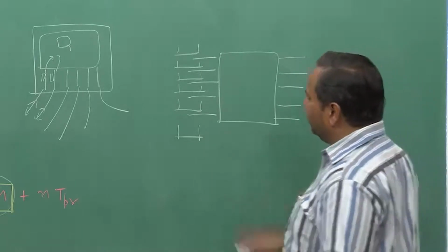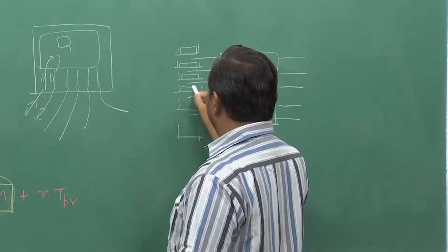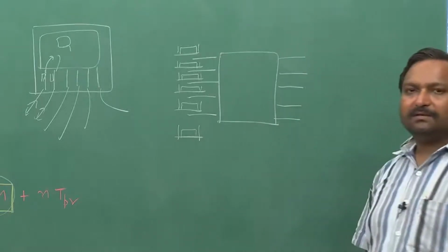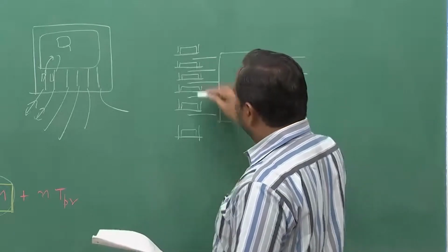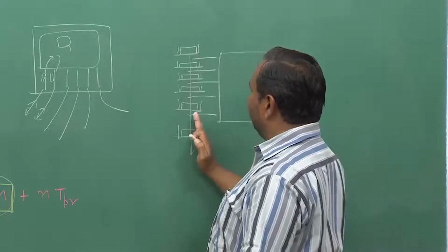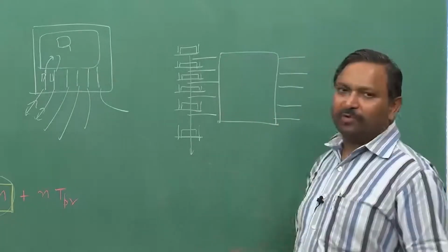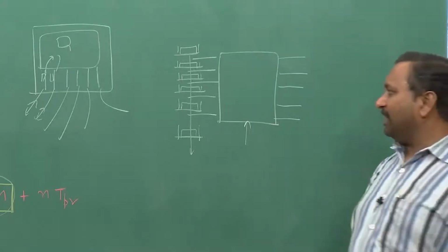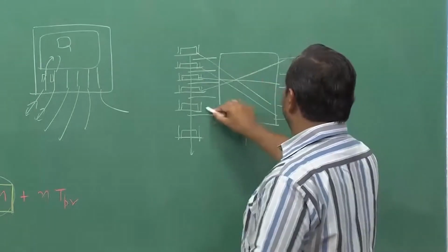Then what happens is the packets will be coming only in this slot, these are fixed length packets, and I can tap these packets. Based on when these packets come, I can decide what the crossbar state will be, which packet should go to which outgoing port, and I will set up a circuit through this crossbar so that these packets go to the specific designated ports wherever they want to go.